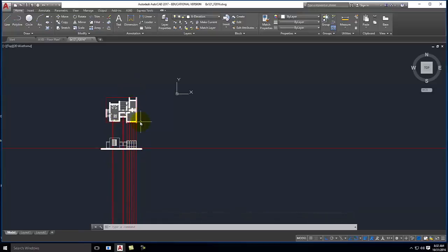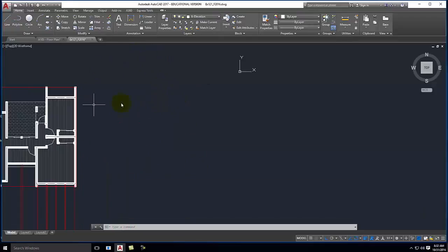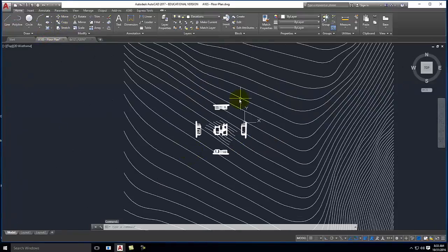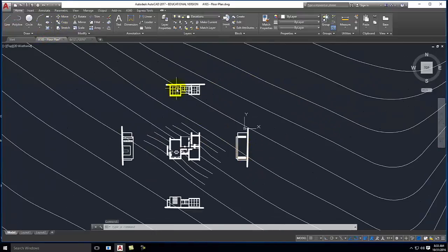It's easy to say, okay, well, what's happening here on this wall goes to there. The truth is, though, that this has a relationship all the way around the building. So this elevation, right, would happen off to this side. And if I turned my head to the side, I could see it. Right? Likewise, if I turned my head the opposite direction, I could draw the elevation right here. Furthermore, if I wanted the north elevation, I could draw it upside down on this side. So if I look at the one that I have complete, you can see that I've actually drawn the building elevations on all sides, right? But they're folded out from that particular side.